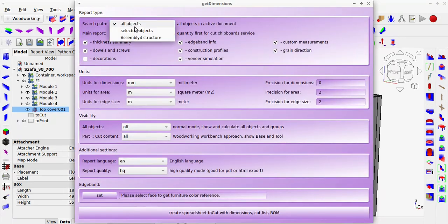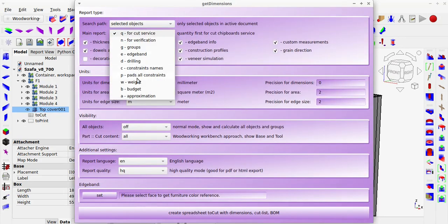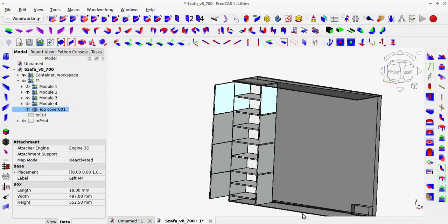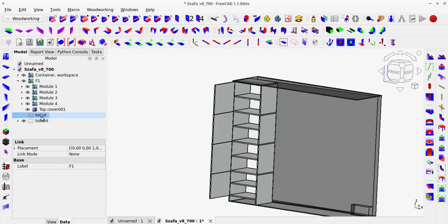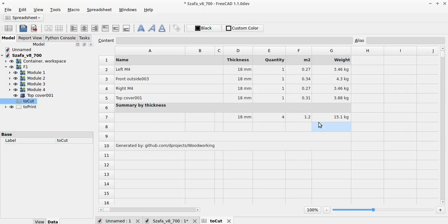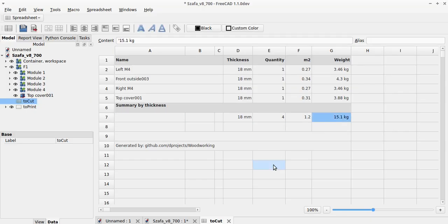It is a good idea to weigh such modules and, if necessary, redesign the furniture so as not to place unnecessary strain on yourself. In this case, to reduce the weight of the module, you could use a 3mm HDF back, also detach the front and consider a removable shelf.